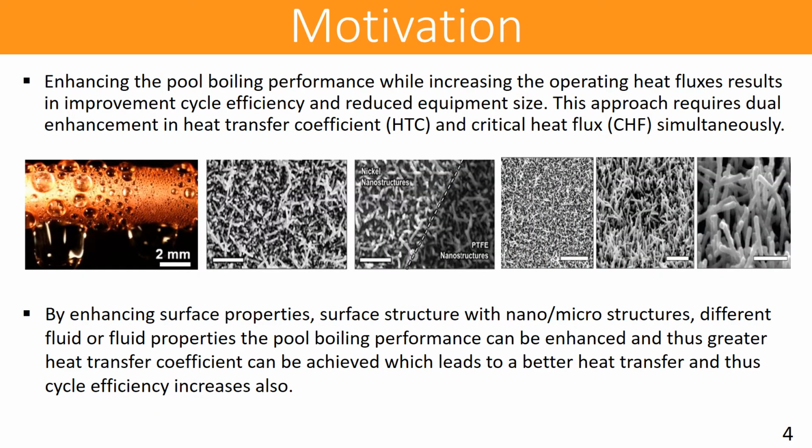Talking about enhancing pool boiling facilities, it can be done by enhancing the surface properties, also by incorporating micro and nanostructures onto the surface. Also, we can enhance pool boiling by changing the fluid property or by using different types of fluid.